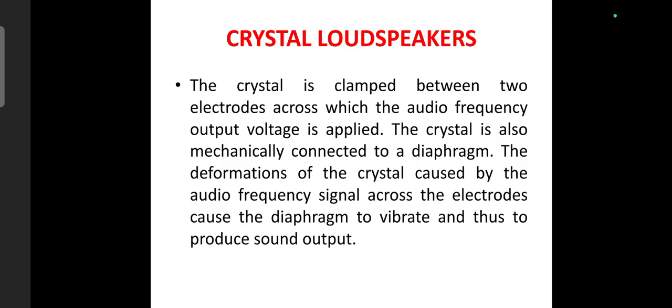Earlier, while studying crystal microphones, we learned that applying mechanical pressure to a piezoelectric crystal produces an electrical voltage. In a crystal speaker, the reverse process takes place. When an alternating electrical signal is applied to the piezoelectric crystal, the crystal expands and contracts continuously. These small mechanical movements are transferred to the diaphragm attached to the crystal. As the diaphragm vibrates, it creates sound waves that travel through the air.